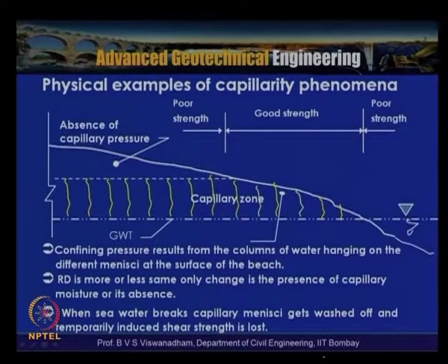So when the seawater breaks, the capillary menisci surrounding these sand particles get washed off, and the temporarily induced shear strength is lost.